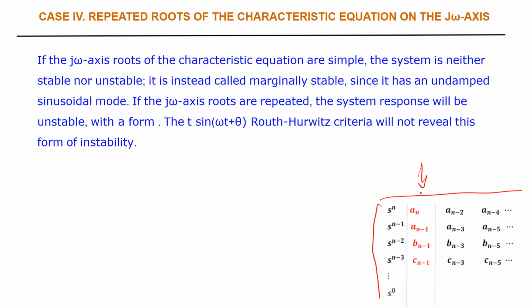The first case we said, all the elements in here are non-zero. But during the process, if let's say this is 0, we cannot proceed. So we change this one into, what did we say? Epsilon. Epsilon, great. And then we proceed. This is one special case. The other special case is that this row, the entire row is 0. In that case, again, we cannot proceed.